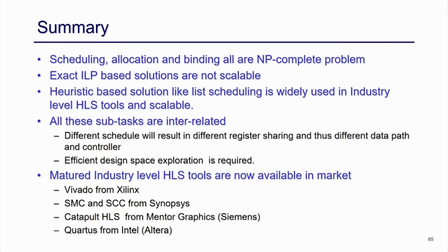Now we will come to the summary of these steps. We found that all these steps, scheduling, allocation, and binding, are NP-complete problems. So, an exact solution is not asked for most of the time. You usually apply a heuristic-based solution like list scheduling to solve this problem.